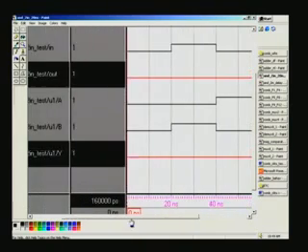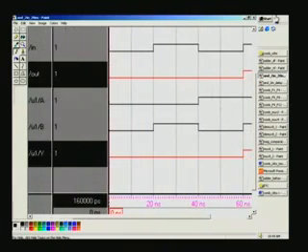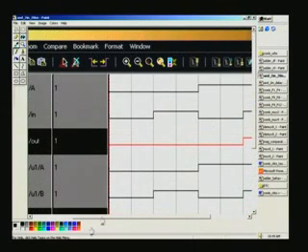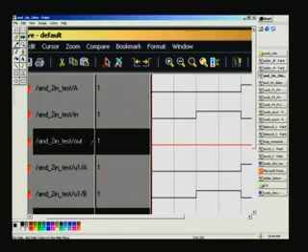And let us go to the different inputs. In the test bench, the two inputs are A and in. This is 0 level and this is 1 level here. So again for the in input, this is 0 up to 20 nanoseconds, and for the next 20 nanoseconds it is 1. So the combination that you have as per the truth table that we have seen earlier for this test bench is 0 0. Corresponding to 0 0, this is an AND gate, so you expect 0 as the output, and that is precisely what you have here.